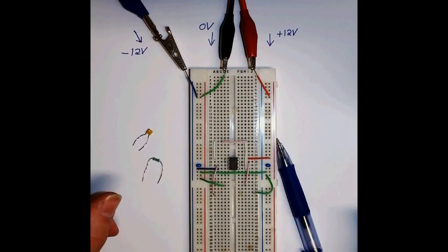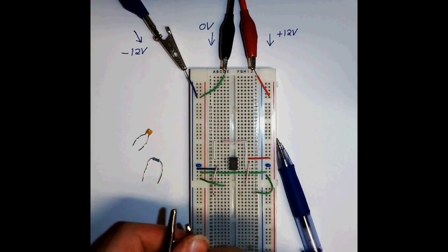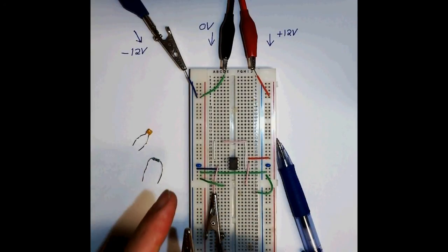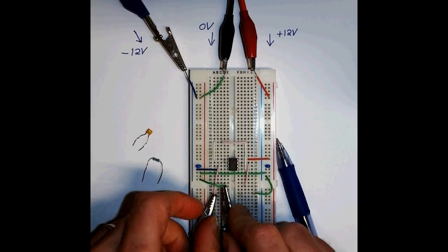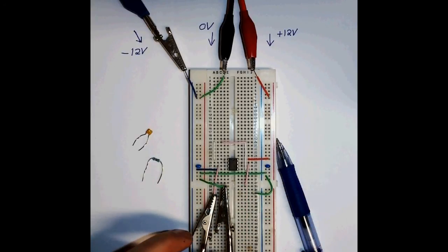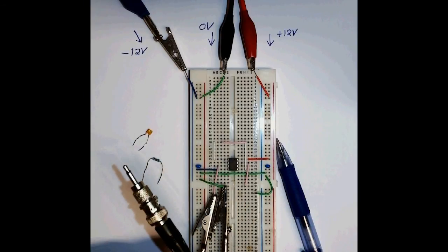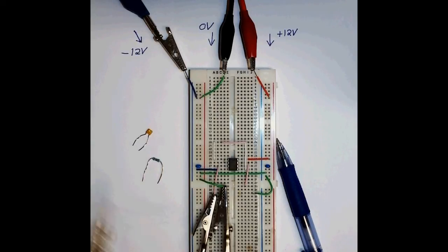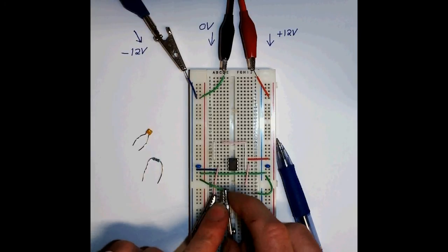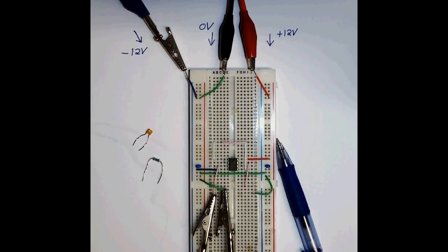Done. All I need to do now is connect up the output from the VAM's output to the input side of this circuit. So that would involve connecting maybe a pair of crocodile clips up like this. And this is a pair of crocodile clips that I've put on the end of a BNC lead. And the other end of the BNC lead has got a 3.5mm connector on it like that, and I can just plug that directly into the VAM. Make sure that those two crocodile clips don't touch, otherwise we're in trouble. Possibly a bit of blue tack in there just to keep them apart would be a good idea.